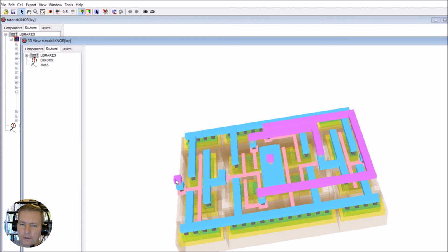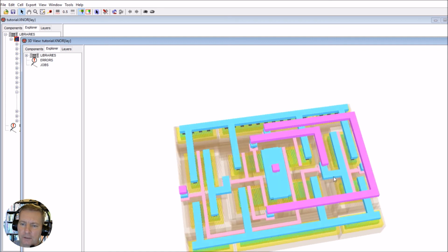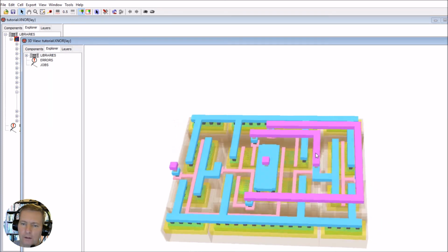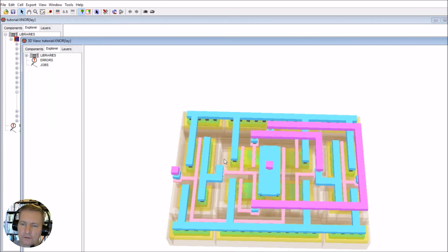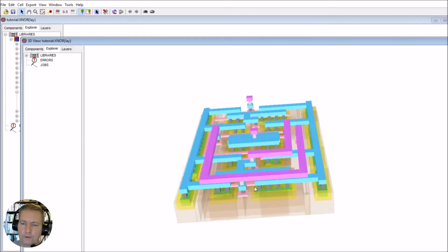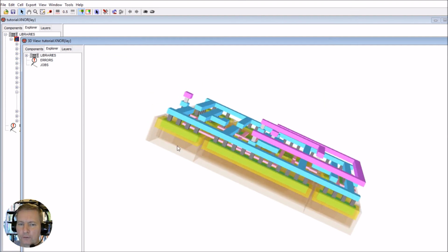So this is giving us our A and our A dash, and this gives us the blue line here, the red line here is giving us our B input, and we're getting our B dash at this point here, and it feeds into our CMOS transistors at the top and our NMOS transistors here at the bottom. So that's our exclusive NOR function. Now there are other ways of implementing exclusive NORs that don't use as many gates as this.